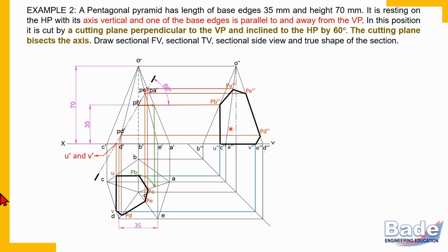Remember, a section is a surface. It is a newly generated surface due to the cutting. Therefore, a section has a closed boundary. Don't forget this. A section has a closed boundary and no other visible edge or hidden edge inside the section. The section is to be hatched, but we'll do it later. First, we'll now make the remaining portion dark. The portion nearer to the XY line is the retained portion, so we should make it dark.